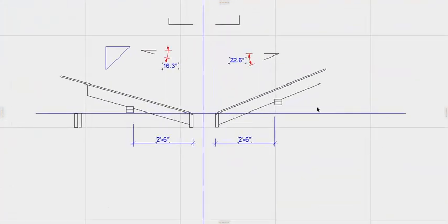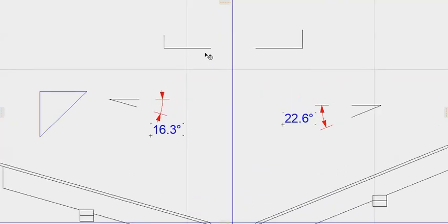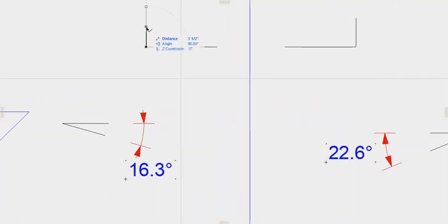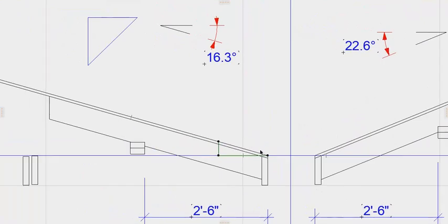So what I've done is I've set up how you might start doing this. And I'll start with the left side here. This is my 3.5 and 12. So you've got your lines here as your guides, and you get your tape measure and you measure 3.5 and you measure 12, and it might not be as easy as what I'm doing here, but you can do it. And you would draw that there and you would snap through and pull that line right on through, and that is the top of your plywood.